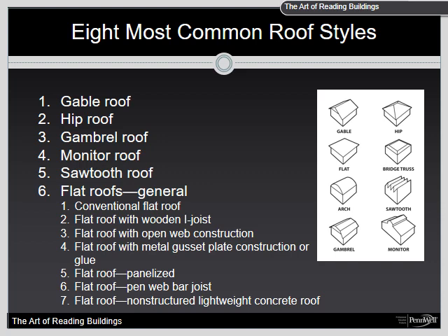One of the greatest hazards is misidentification of a lightweight construction roof. Identification can be enhanced by an intimate knowledge of your district and pre-fire planning. Actually, the presence of 2x4s and rafter tails under the eaves is an excellent indicator of lightweight truss construction.